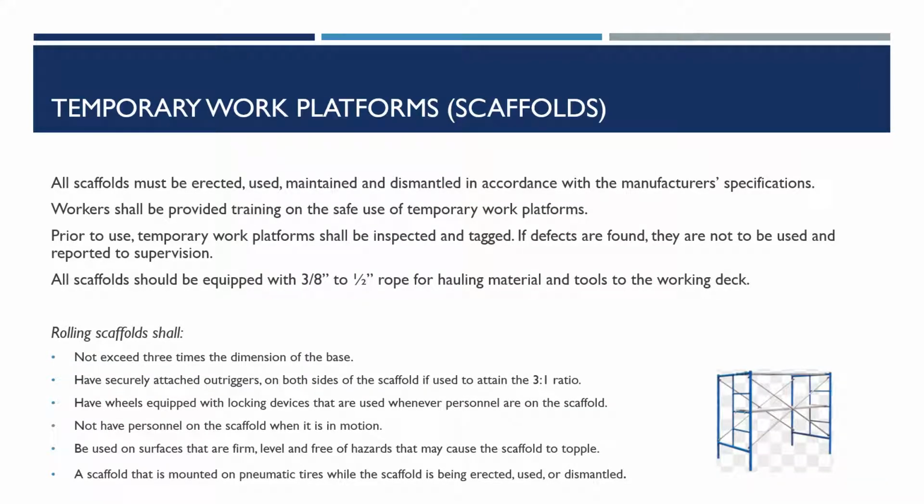Temporary work platforms. All scaffolds must be erected, used, maintained, and dismantled in accordance with manufacturer's specifications. Workers shall be provided training on the safe use of temporary work platforms. Prior to use, temporary work platforms shall be inspected and tagged. If defects are found, they are not to be used and are reported to supervision. All scaffolds should be equipped with 3/8 to 1/2 inch rope for hauling material and tools to the working deck.